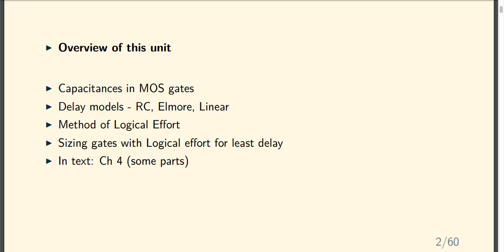But every MOS transistor has something called a parasitic capacitance that is associated with the structure. Unavoidable. There is no way to make it zero, so it will always be there. And similarly, every wire also, the wire is not floating in the air. There is going to be some insulation between the wire and the substrate. So that also forms a parallel plate capacitor. And these are all the sources of delay in the RC domain.